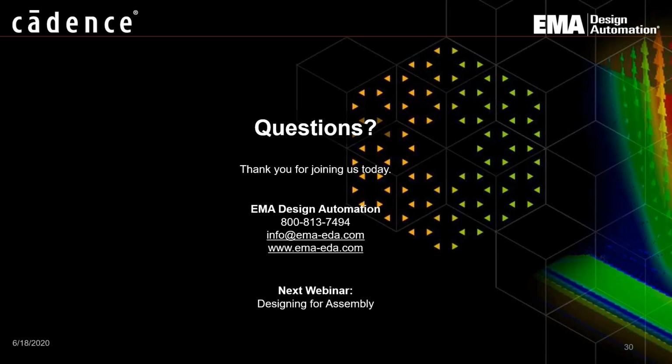If the question is about thermal vias, then they will be inside the chips. And again, that will be for the Celsius thermal solver in this tool. We could resolve true 3D, we could resolve 2D. We could also implement the traditional conventional thermal parameters. For package and board, we have theta JA, JB, JC, two-resistor model, and Delphi model included. And for others, engineers can implement some thermal resistors inside the assembly.